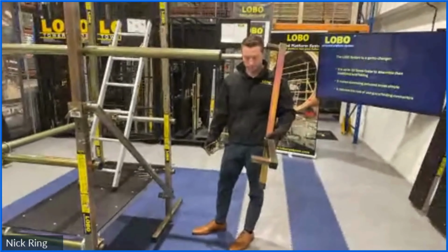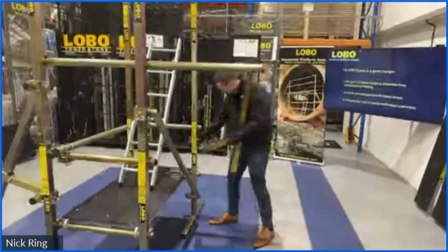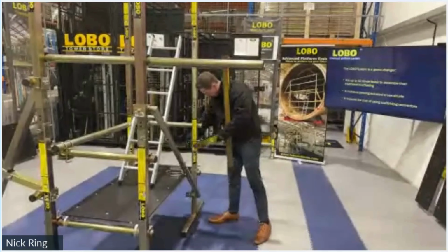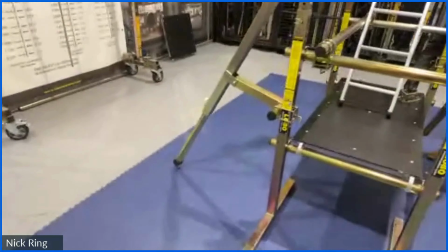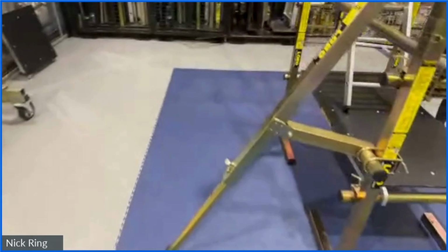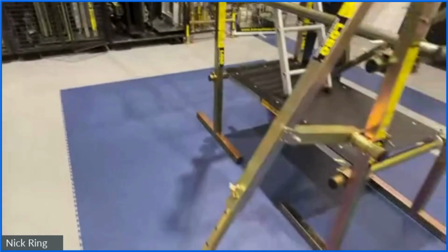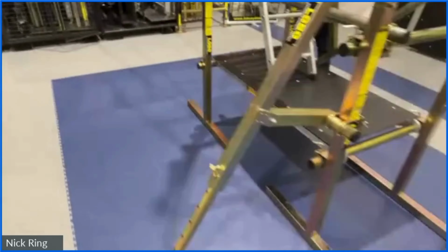It is a LOBO outrigger. It has a 20-second fit time. It's a steel component, and we've got them on this leg as well. So you put these on every available leg. And this has the function of making the system wider. As you can see, it is 20 seconds. Then you deploy the rubber foot, and that added 0.9 meters to the base, just like that.